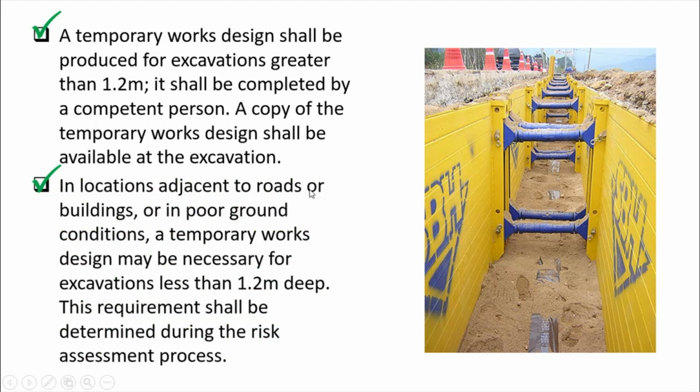In locations adjacent to the road, buildings, or in poor ground condition, a temporary works design may be necessary for excavation less than 1.2 meter deep. This requirement shall be determined during the risk assessment process.